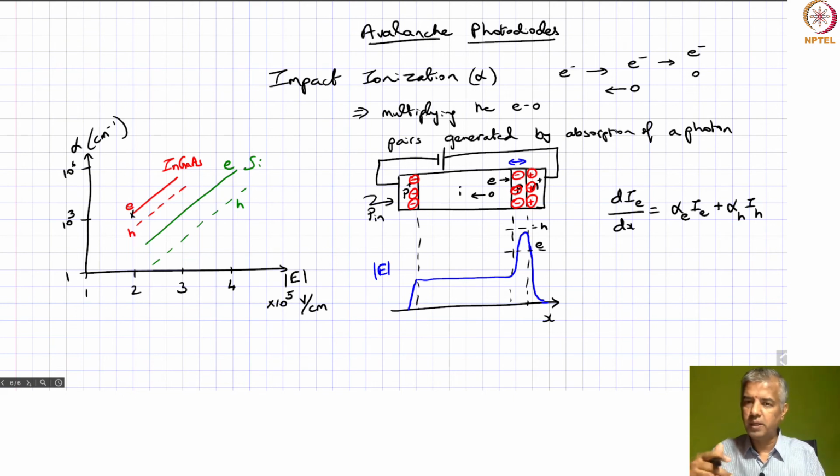So you're able to keep increasing your bias voltage and keep getting higher and higher multiplicative gain for a silicon photodiode without incurring extra noise, up to a certain voltage. That voltage is much higher for silicon compared to indium gallium arsenide. So you're able to effectively get much higher optimum gain values for silicon compared to indium gallium arsenide.